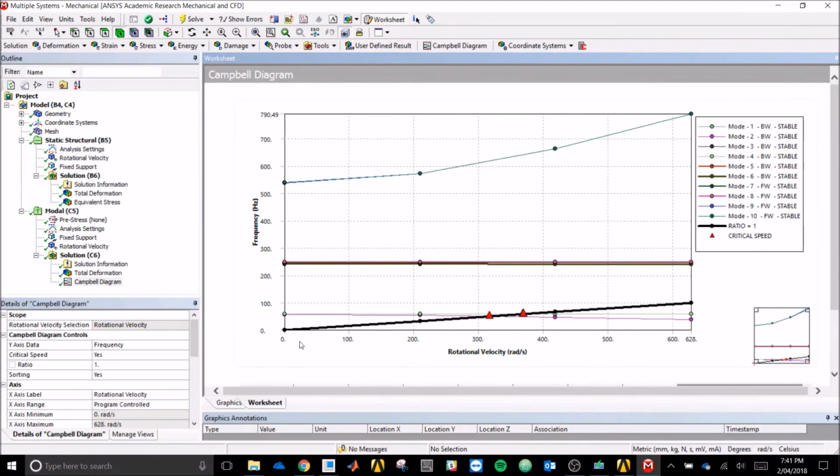So you can see as our fan accelerates from 0 to our desired operating speed, there's 2 instances called critical speeds where the rotational frequency of our fan matches a fundamental mode. And this is highly undesirable or potentially dangerous, and you want to avoid that. So in some cases it can be unavoidable to pass through these situations as long as you do it quickly, but you wouldn't want your fan operating around these speeds for any extended periods of time.